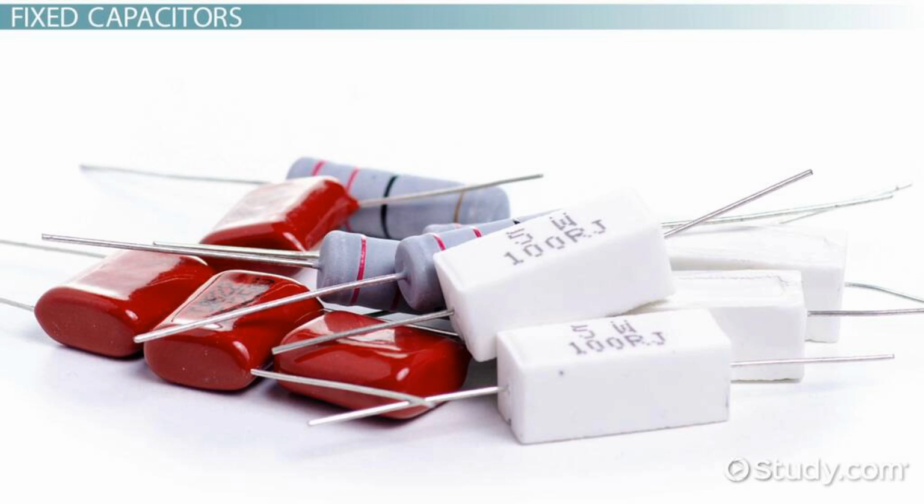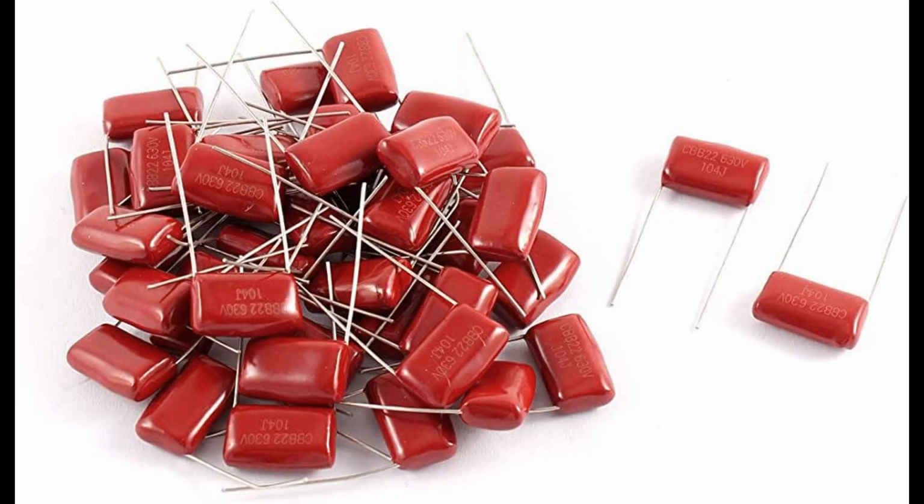4. Role of dielectric, plastic film. The plastic film in film capacitors serves as an insulator that separates the two electrodes. It prevents the flow of electrical current directly between the electrodes, while allowing the electric field to exist between them. Energy storage. The dielectric is where the energy is stored in the form of an electric field. Dielectric breakdown. If the voltage exceeds the dielectric strength of the plastic film, the capacitor can fail, resulting in a short circuit or breakdown of the insulating layer.